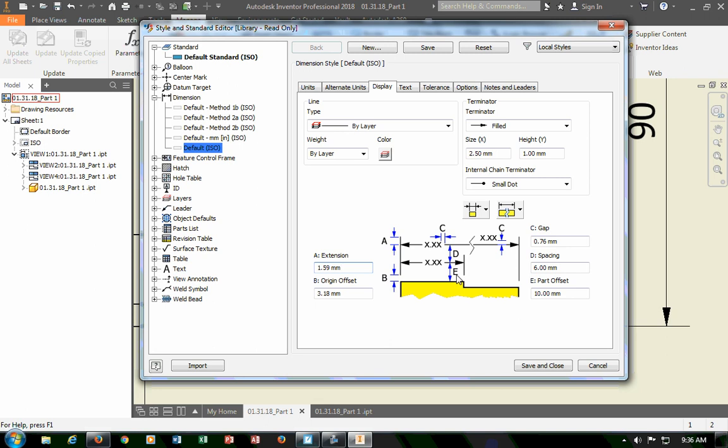The distance E, you see distance E? Distance E should be 1/2 inch away from the part printed, 1/2 inch, which in metric would be 0.5 times 25.4, so that's 12.7. Whoops, I just changed the wrong box. Don't worry, it'll tell you. Dimension E is the 12.7. Dimension D is supposed to be 3/8 of an inch, 0.375 times 25.4. So that's 9.525.